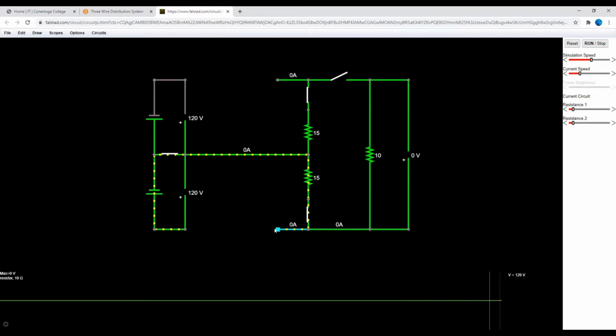The reason for adding these resistors to these 2 lines is because all wires have an amount of resistivity. They have a wire resistance, and that wire resistance is going to cause a voltage drop on the wires, and it's going to cause what is called an I squared R loss. And that's why I'm adding them, in order to determine the I squared R loss.